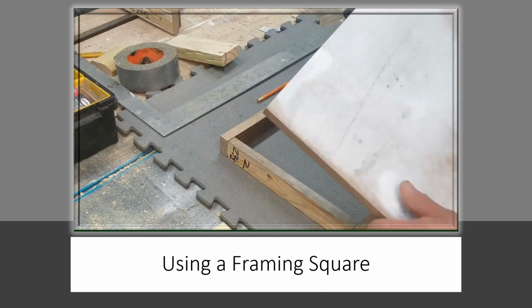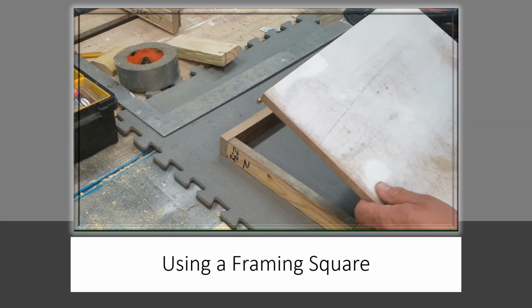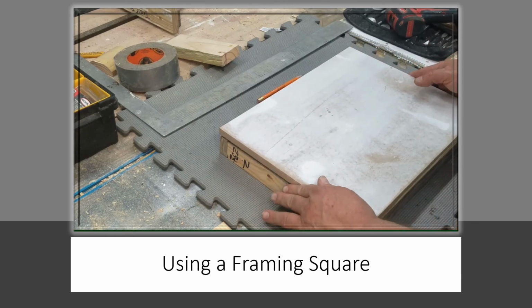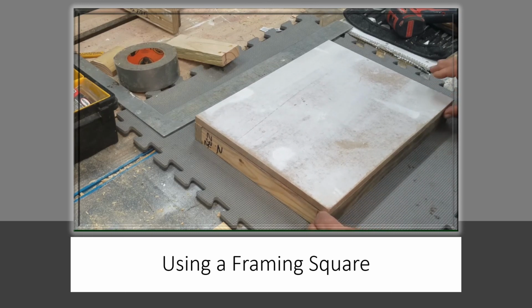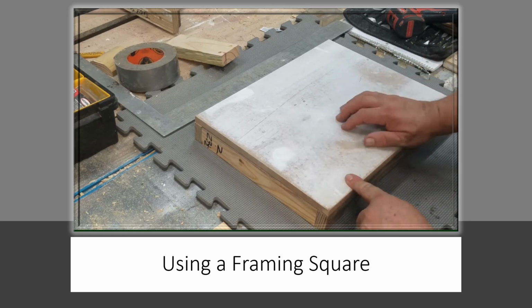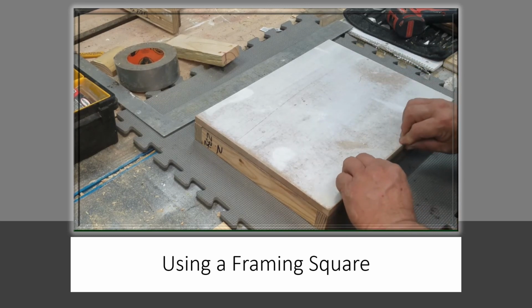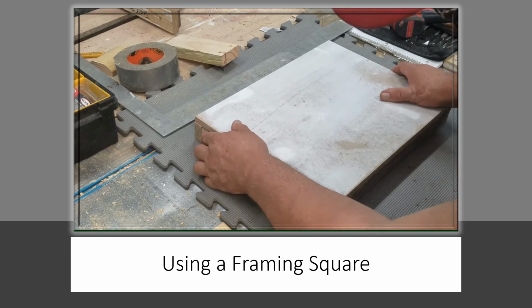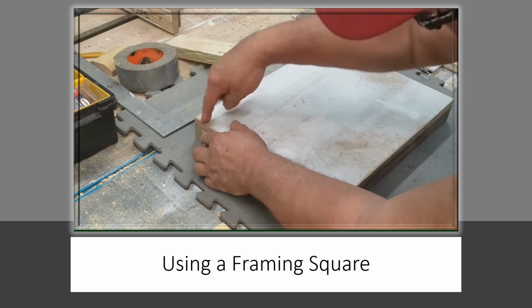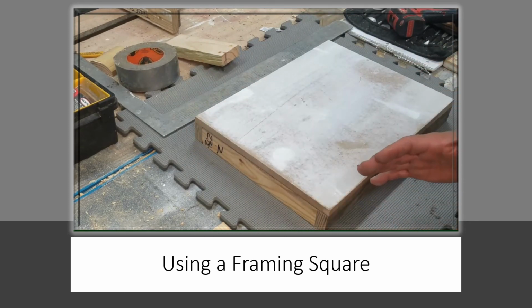So if you're putting plywood on top of a frame you built, the easiest way to do it is to square it up. If you know the top is square, just get this line here perfectly flush. Go ahead and nail it, screw it, whatever you're going to do. Once you get it screwed, if this is attached, it can't move, then I can just push this over till it gets there, put a nail in it there, and it's square. All right.